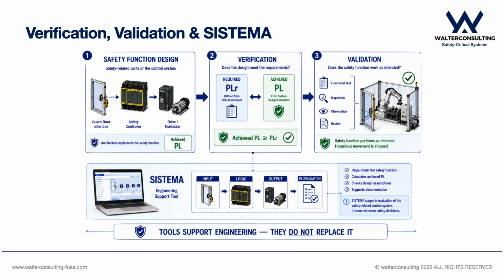For our robotic cell, this means more than evaluating reliability data on paper. Engineers must confirm that opening the guard door really produces the required safe reaction, that the complete function behaves correctly under the relevant operating conditions, and that the specified safety requirements have been fulfilled.